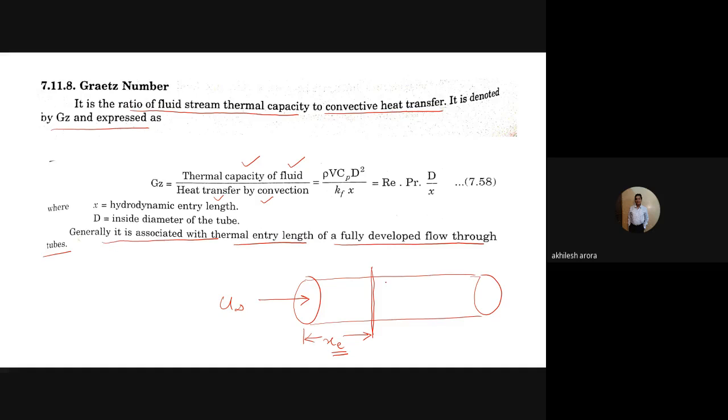After this, if you see the velocity boundary layer, it would be perfectly developed, like this. Otherwise, if you take any other section here, it could be something like this. At the center it is not fully developed, and at the entry the profile will be a straight vertical line like this.